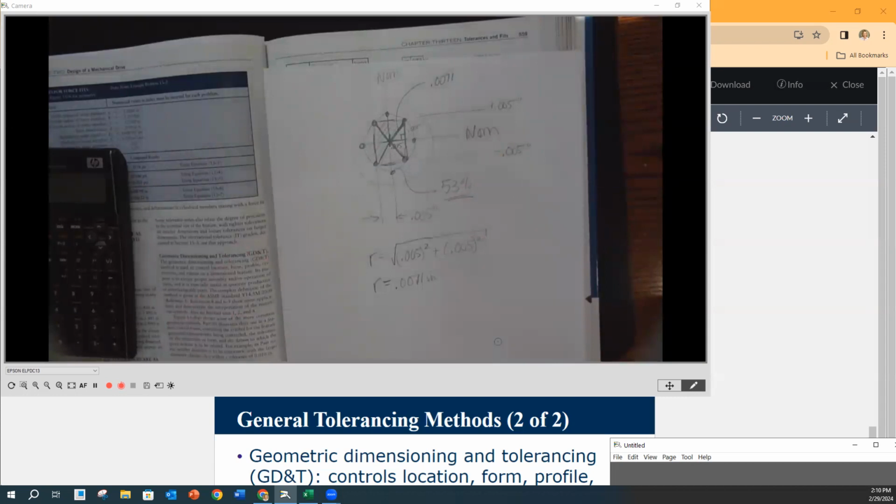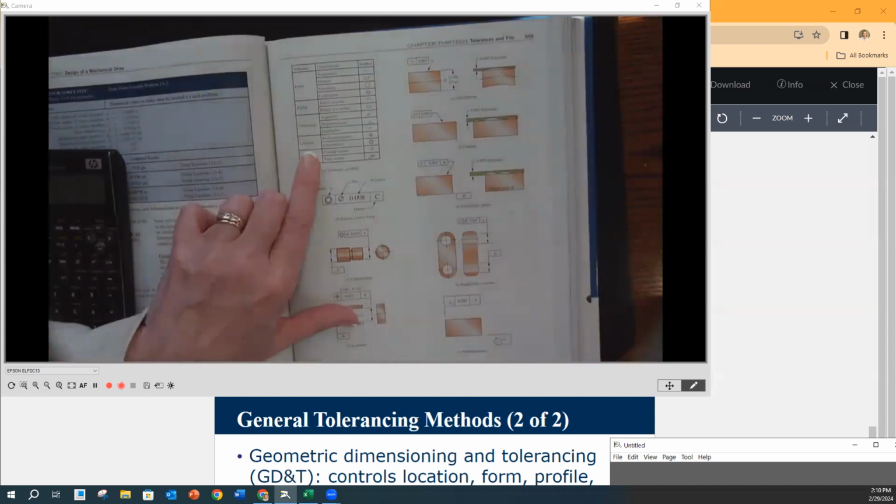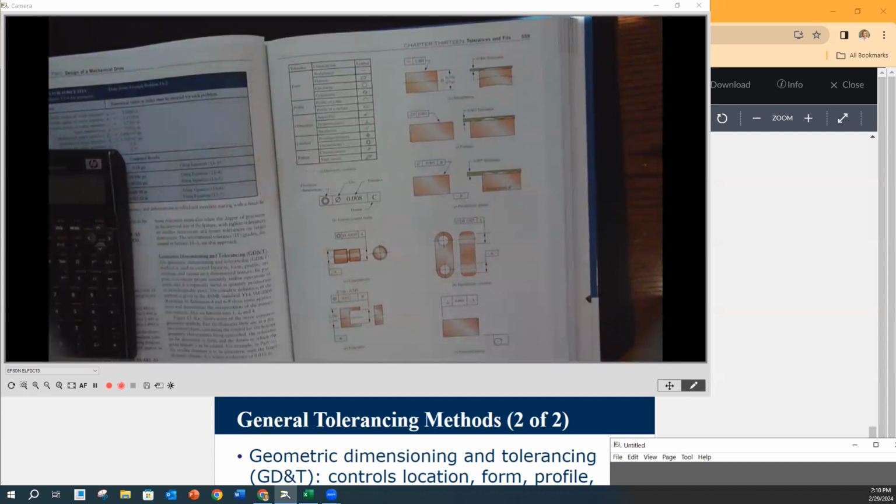So my whole point there is we want to be putting position when we're locating, especially hole patterns, features that are located from ends of things. They should have position on every single one of them. You need to be considering that. And then applying your tolerance based on, is it a fixed or a floating fastener application, right?